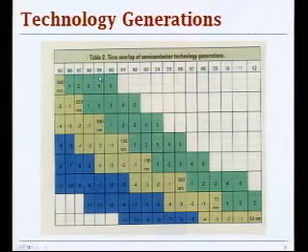And for example, in 99, you first introduce 180 nanometer technology, and you keep using that technology for the other 5 years in the future. And today, for example, quarter micron technologies have already been phased out. And you can also see these funny numbers like -1, 2, 3, and 4. What this means is basically just a development cycle. You need a certain number of years to develop your technology for the full manufacturing capability, and then you use it for a certain period of time in the future.